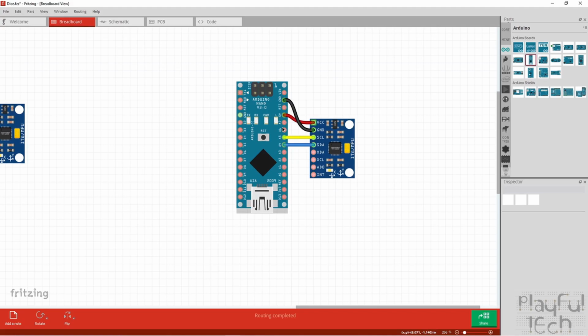But here's the thing. On an Arduino, when you use the I2C Wire library, when you're not writing a signal, these two pins are initialized using the onboard pull-up resistors, which are pulled up to 5 volts. But the pull-up resistors on an Arduino are very weak.